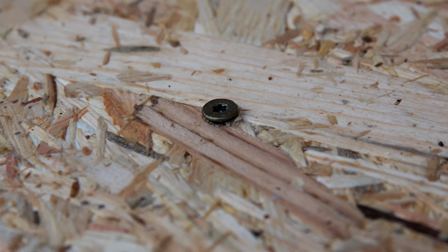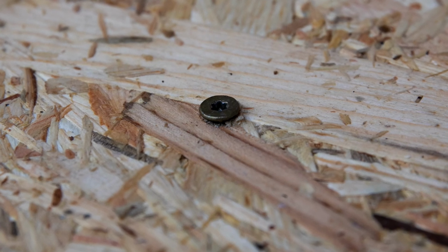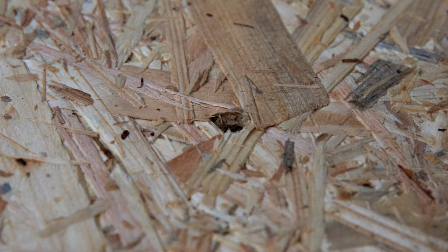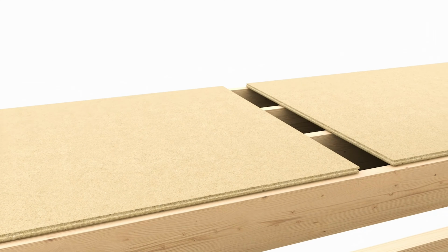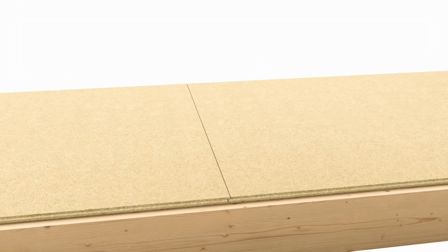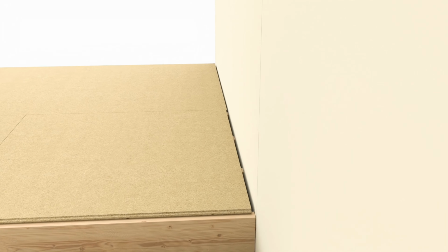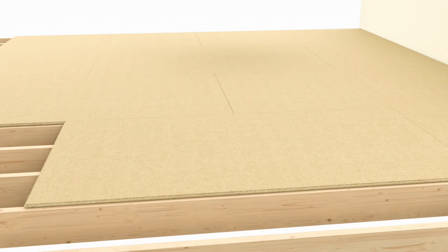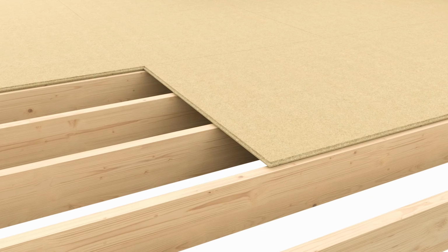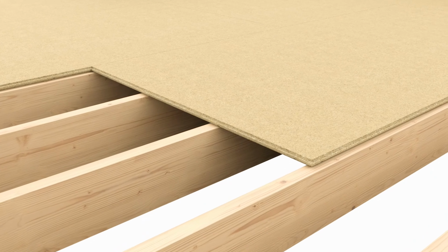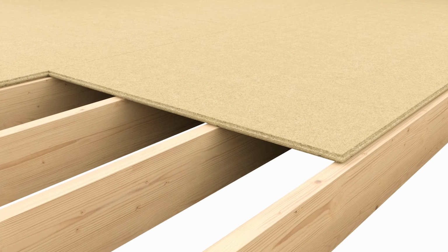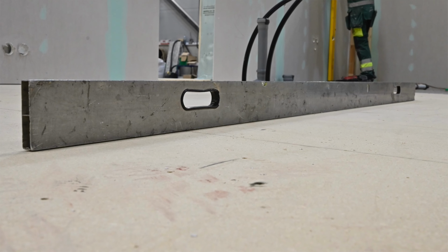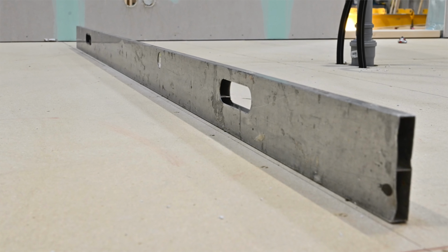The heads of the fasteners must not protrude above the surface of the panel or be recessed into the panel. The boards are usually joined with a tongue and groove connection, except at the edges where the boards are cut to size. The cross joints of board rows should not align with each other. Depending on the manufacturer and the type of boards, it may be possible to leave the board's end joints between the beams if there is a corresponding tongue and groove connection provided by the board's manufacturer. After installing all the boards, the entire floor's levelness must be checked.